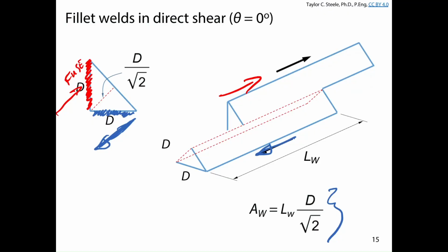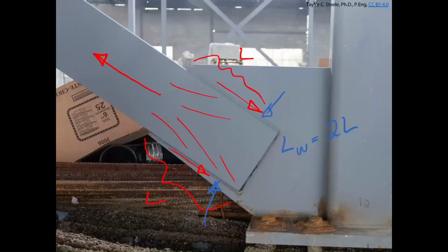Because that's just, if we come here, we've got a force that's applied through this tension member. That force has to come through these welds, and by the direction of the load, that loads those welds in shear. We're going to see in a minute when welds can be in tension. We'll talk about differences between shear and tension in welds. But it's just the way that the loads are getting transferred here. It's taking tension through shear welds along the length of those two welds on either side.